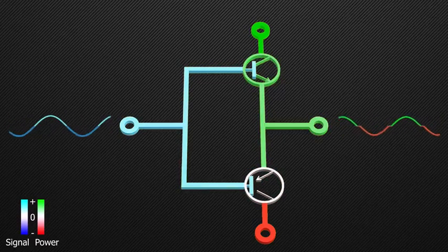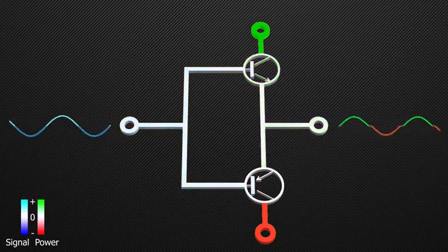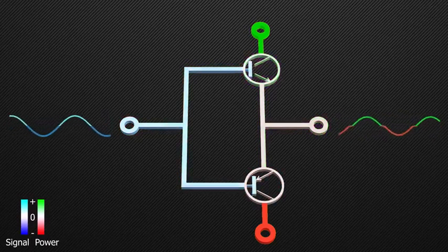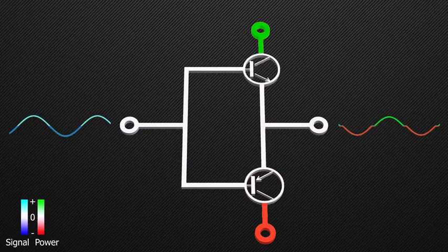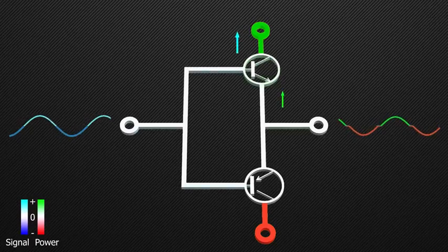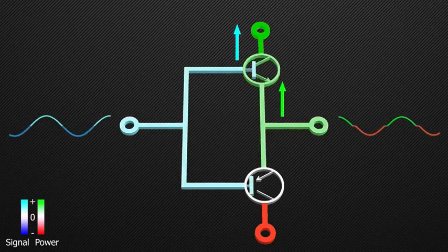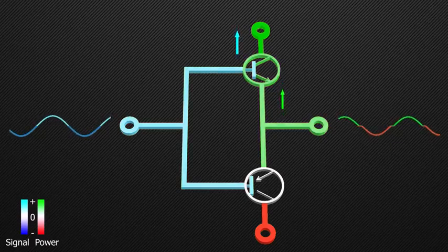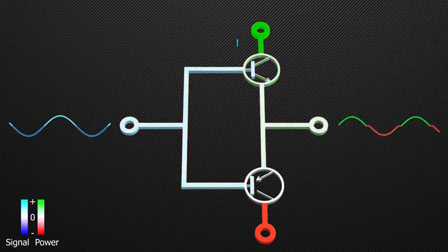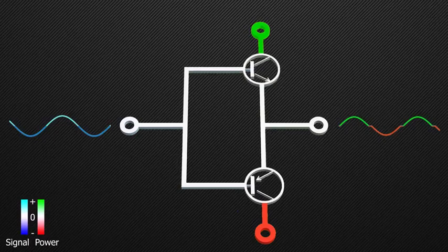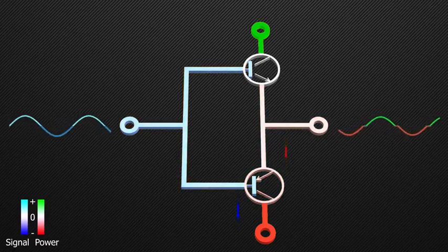Now, you would know that a transistor requires 0.7 volts between base and emitter to turn on. Thus, during the positive cycle, until the voltage at the base is above the cutoff voltage, the transistor is in its off state, and the output voltage is 0. And when the voltage at the base increases above the cutoff voltage, the voltage at the emitter starts to increase, following the base voltage, until it reduces to below the cutoff voltage. Similarly, in the negative cycle, this transistor is off, until the voltage at the base reduces below the cutoff voltage, and then it follows the base voltage.